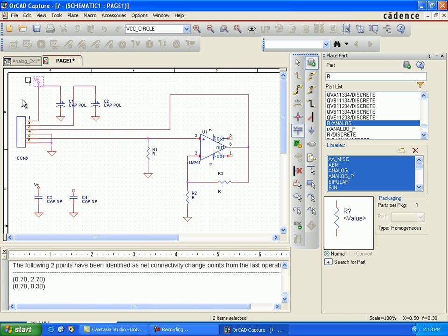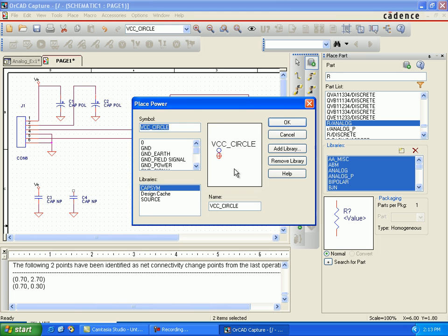On pins 1, 2, 3 we gave positive and negative 12 volt dual supply, and the voltage for the op-amp is normally 15 volt positive and 15 volt negative, so it works on that dual voltage.